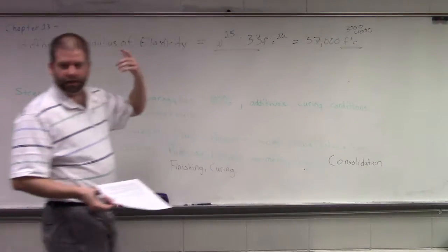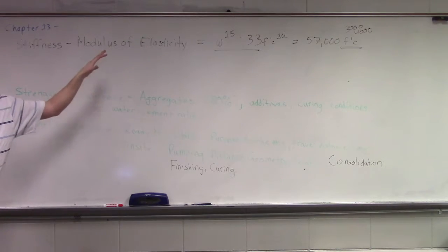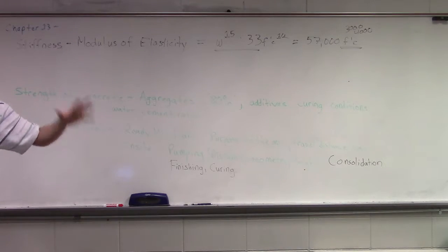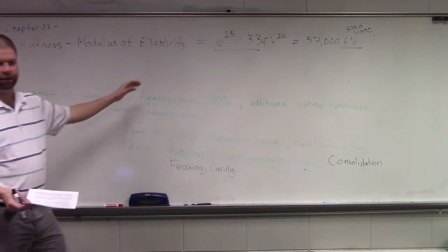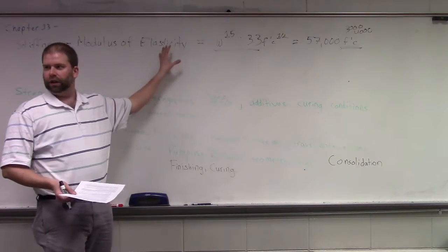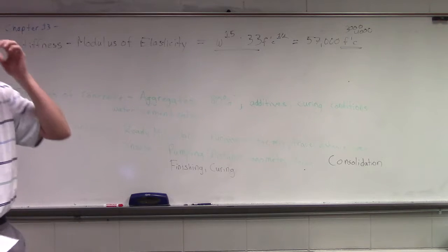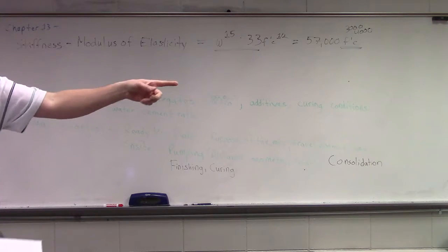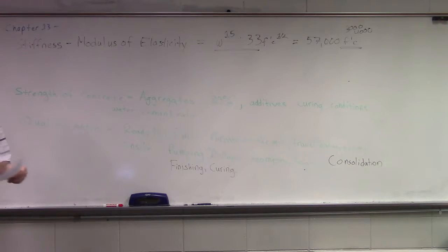So at ASTM, we just got done doing a round robin study because the data that we had was good for concrete with a compressive strength of about up to 9,000 psi. No one's interested in modulus of elasticity of concrete that's 9,000 psi or less. We're doing it at 12,000, 16,000, 20,000 psi, so everything had to be redone. So that machine that we bought, long-term we'll be able to run modulus of elasticity. It's just getting the equipment, so a little lower down on the scale of importance currently.